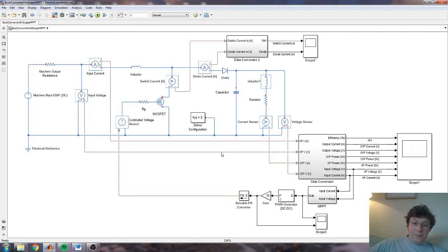You'd certainly be able to hear it, especially the wound components will have some vibrations in them due to the change in flux density. Same as a transformer in the electrical power system hums when you're near it. It hums whether you're near or not, as long as it's got some current in it. So you wouldn't usually choose to run at a kilohertz, but it's just an example for the MPPT really, not so much for the converter.